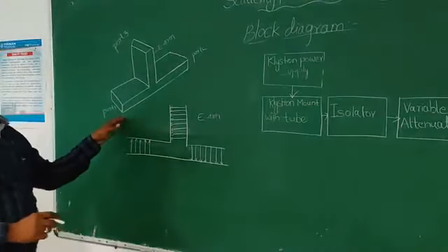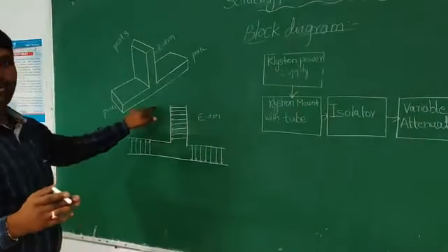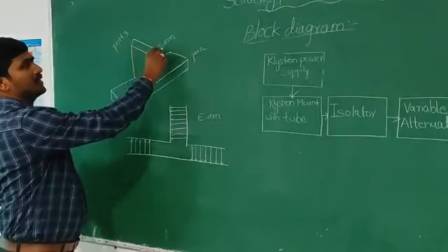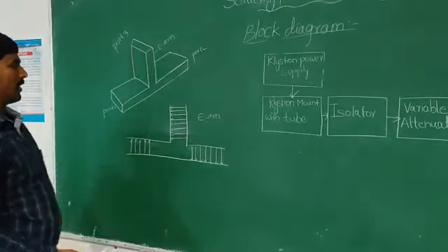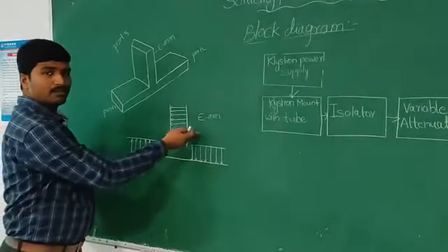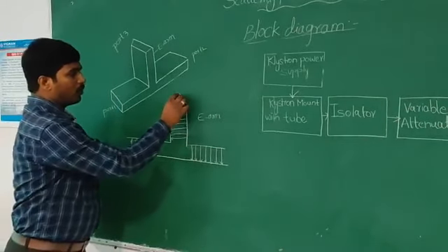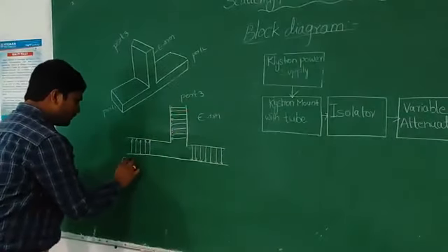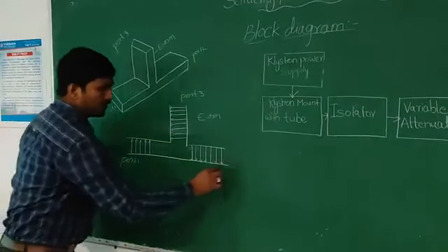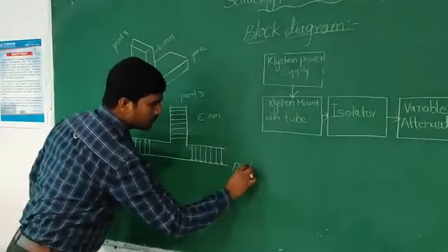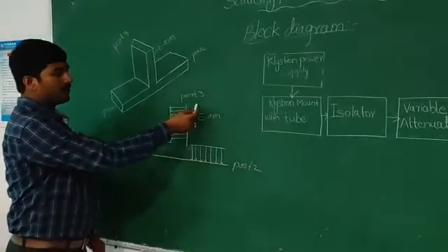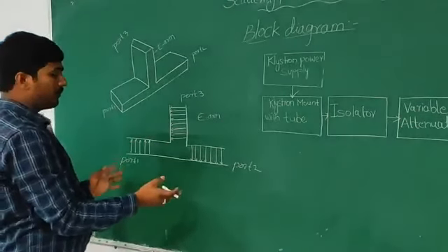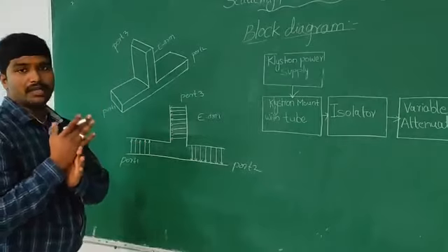The E-plane T has three ports: port 1, port 2, port 3. The vertical arm is called the E arm. When we apply microwave power to port 3, the other arms are port 1 and port 2. When applying the microwaves here, the power will be divided equally, but with a 180 degree phase shift.